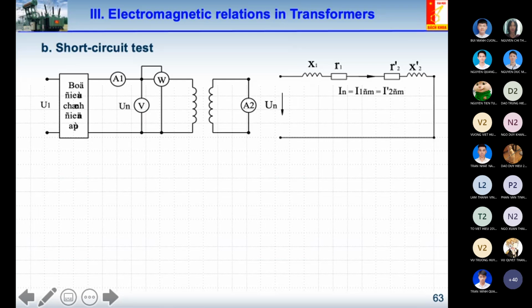But the current flowing in the transformer is very high in comparison with the rated value. So the reason why, if you want to keep the short circuit current flowing in the transformer equal to exactly the rated current, we have to reduce the input voltage of the transformer by using an auto transformer here.